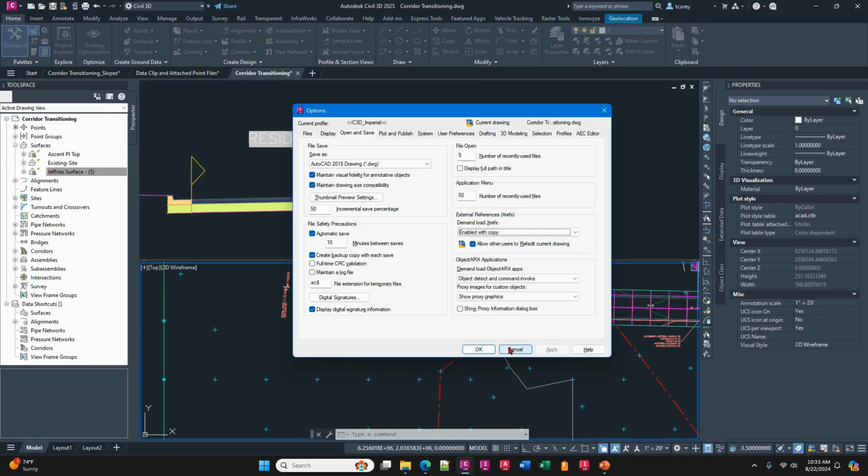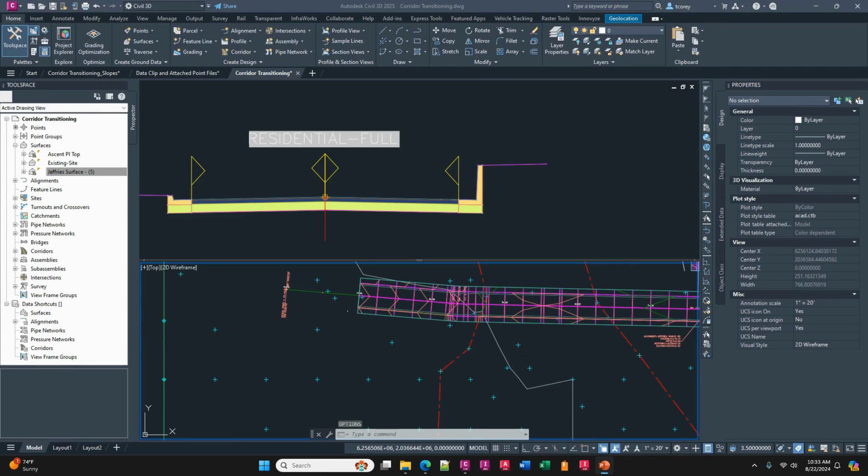And you were also asking about the index control system variable. Index control of 1 creates a layer index, 2 creates a spatial index, and 3 creates both. When you use index control, your drawing file sizes will grow some, because AutoCAD is adding more data into that drawing, the indexes. For programmers, that's how you get to data most quickly, through indexing.